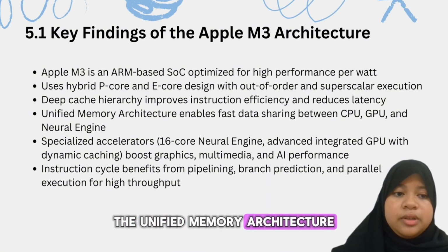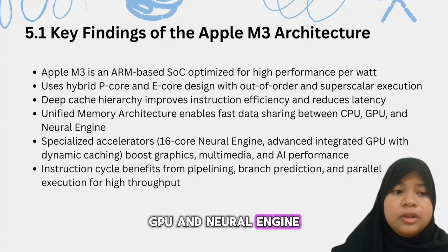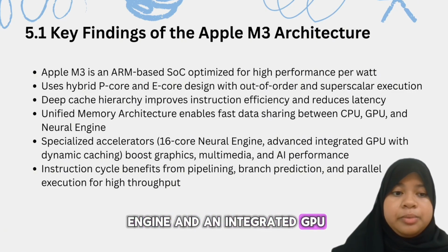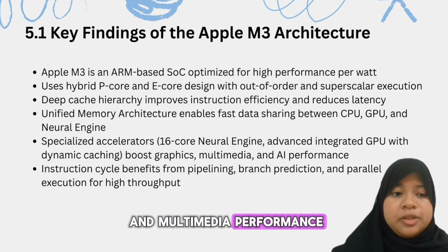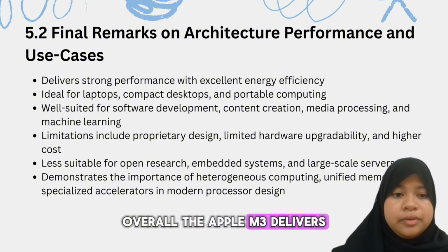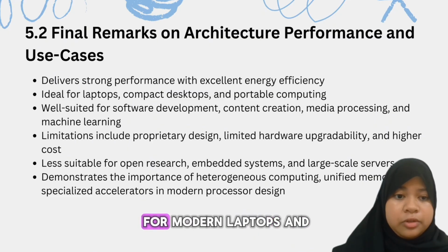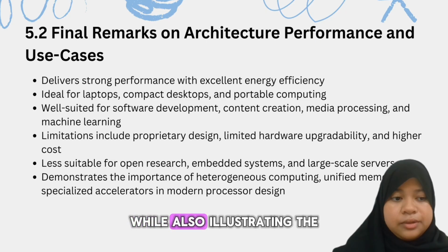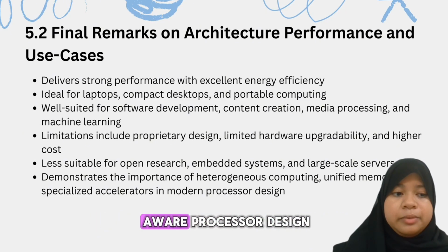The unified memory architecture reduces data movement and latency by allowing the CPU, GPU, and neural engine to share a single high-speed memory pool. Specialized accelerators, including the 16-core neural engine and integrated GPU dynamic caching, further enhance graphics and multimedia performance. Overall, the Apple M3 delivers strong computational performance with excellent energy efficiency, making it well suited for modern laptops and compact desktops, while also illustrating the growing importance of unified memory, hardware acceleration, and energy-aware processor design.